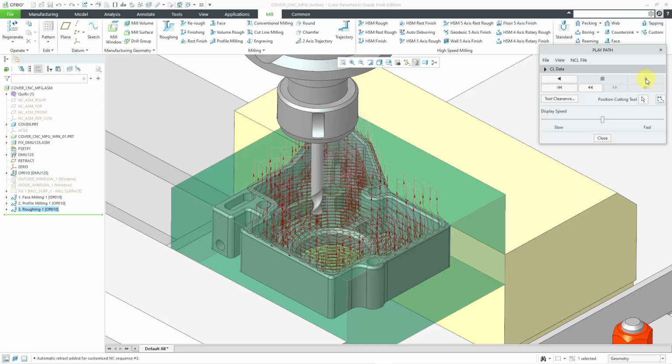So there you have it, just neat, cool stuff. And if you're watching the motion, you're like, hey, it didn't get that close to the walls. Well, in the next video, we will take a look at how to create a re-roughing sequence. Re-roughing is so that you can take essentially a previous roughing sequence and then redo it with a smaller tool in order to get closer to your reference model that you want to generate.